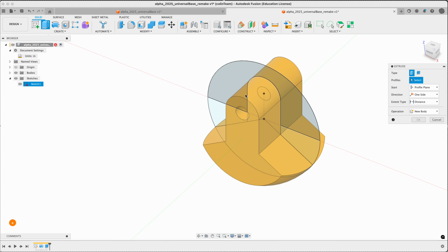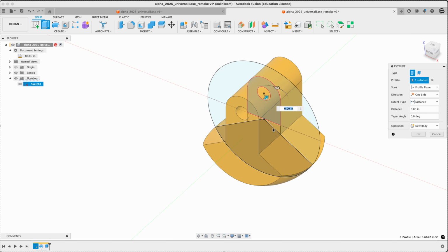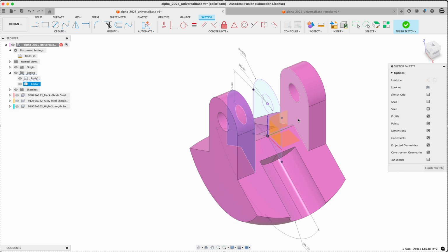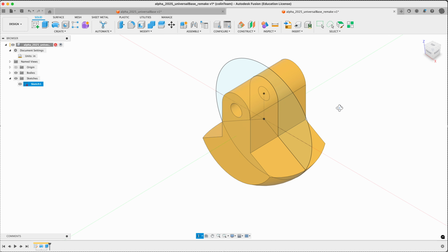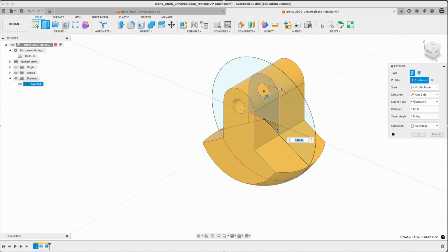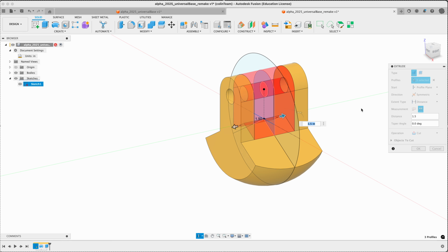So another extrude, but this time only a piece of that same sketch. What do we say again? Distance. We don't have to use the inspect, we can just click both. 1.5. Oh, because I'm flipping back and forth here, sorry. Extrude. This time we're going to be trying to get the right region first. Turn off the preview. There we go. Two sides are symmetric. Distance overall, 1.5. And it should say, oh, you want to cut, which is what we want.